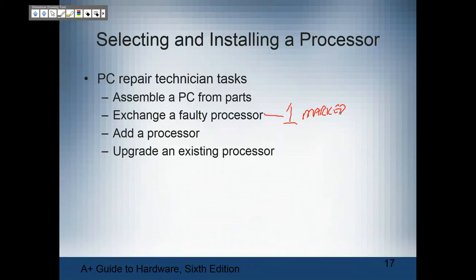Don't take anything out of it. Well, he couldn't resist. So they took the processor out. And then they put the processor back in wrong. So now all of a sudden, after you get done, restart the machine, it doesn't restart. What they've done is turned the processor 90 degrees. And it fit into the slot. They made that to where they're not necessarily going to do that so much. But pin 1 is going to be marked on everything that you do. So you need to be sure that the pin 1 gets lined up.